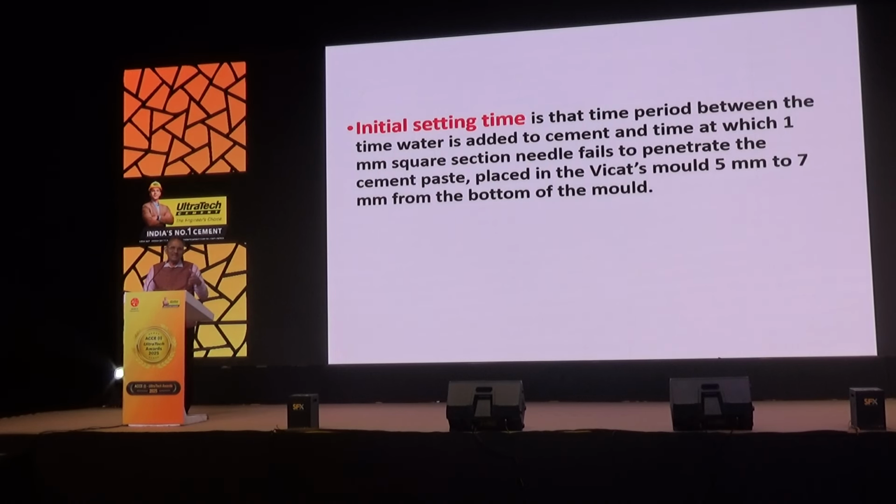Then when we investigated, we found that the lorry, the transit mixer driver, was given the retarder. He was asked to pour some quantity for every 1 hour. He doesn't have patience, so he put the whole quantity in the transit mixer in one go. And it happens even now. Recently also I had a problem in one of the sites where concrete didn't set for 24 hours.